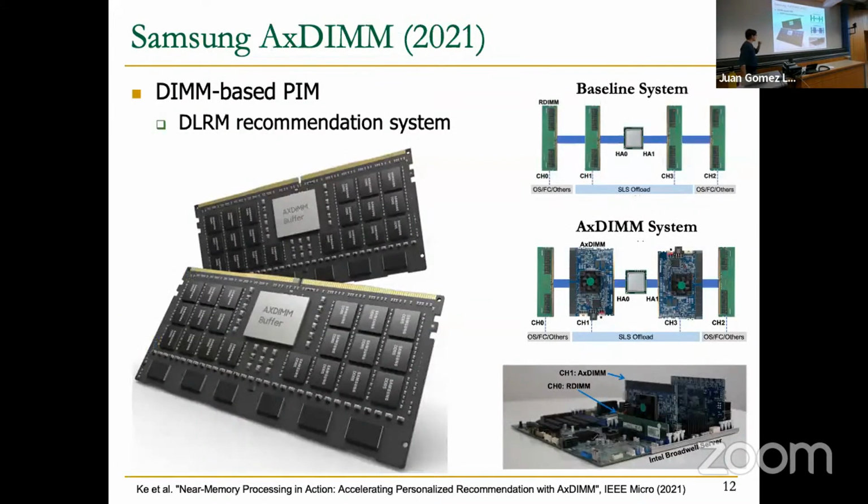And this is the other proposal from Samsung. It's a DIMM-based solution. In this AX DIMM buffer, they will place a small FPGA, similar to the design that you can see there in the prototype, and they have tested this for recommendation systems.